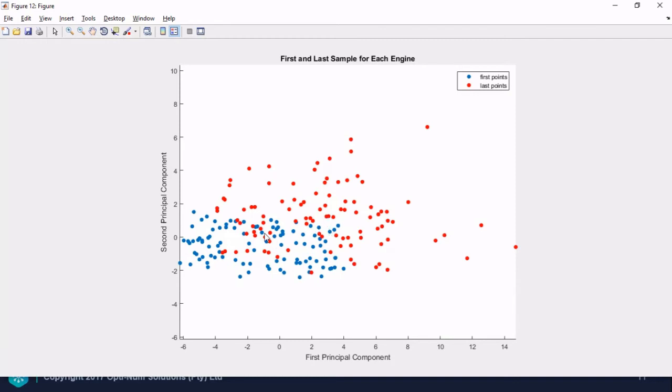So now, the last data points for each engine that fall in this region could indicate that when maintenance was performed on the engines, the engine was still in a good condition. We know that scheduled maintenance was performed on all of the engines, irrelevant of what condition they're in. So we can assume that this region indicates normal conditions for the engines, and data points that lie further out might be an indication that problems are starting to occur and the engine might require maintenance.